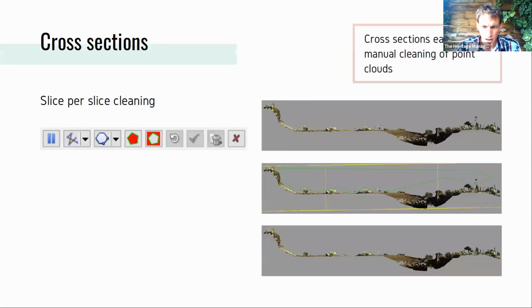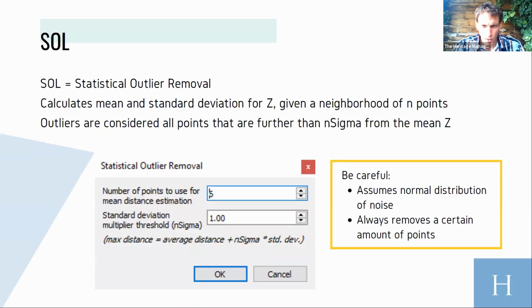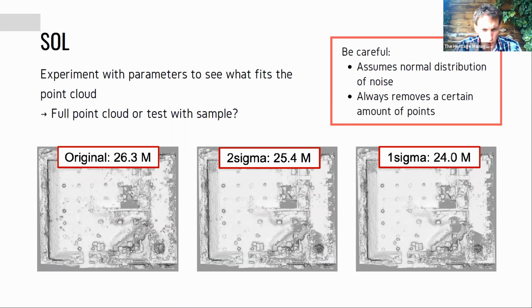So that's happening here in the statistical outlier removal. Why is this still very useful? Well, especially when you're working with data where there are a lot of outliers present in the data itself. So for example, in the Eleusis data, this is terrestrial data, but it is acquired as if it is airborne data. So we have a topographic coverage of a very large site. And it will actually allow you to do some data reduction and some interesting pre-filtering on the original data set.